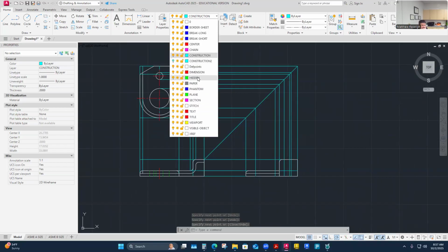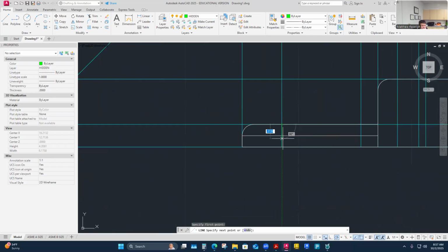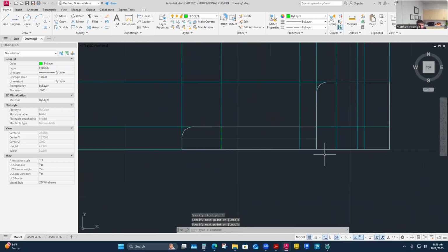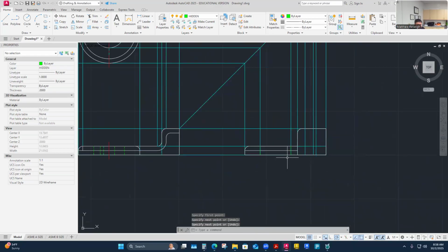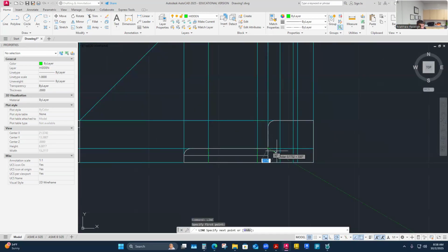And then I'm going to be doing hidden line work here. So I'll just make this easy and do this hole first. That's this hole through again here. And then this is going to be a hidden line across though, where that foot transitions back to the surface away from my view. I would see that as a surface. And that's really as far as that hole would go. The little hole would only be going through this, from the bottom here to that thinner surface.